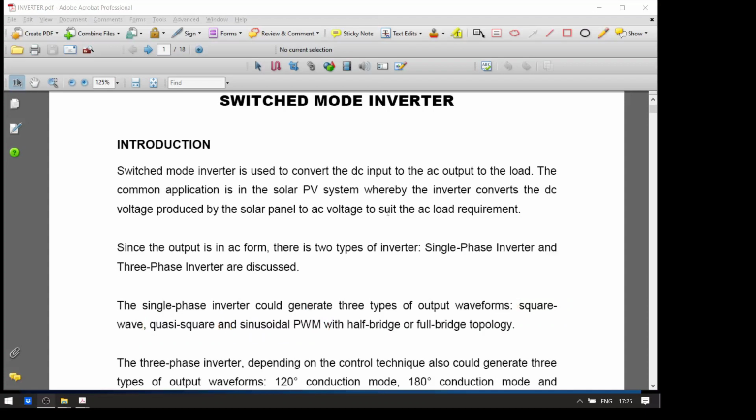All right. So today, the PWM waveforms, which are the control signals to the switches, can be obtained conventionally by comparing two signal generators, which are the sinusoidal modulating signals, and the triangular carrier signals.